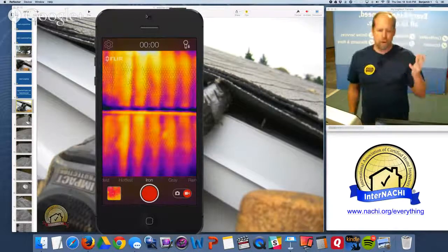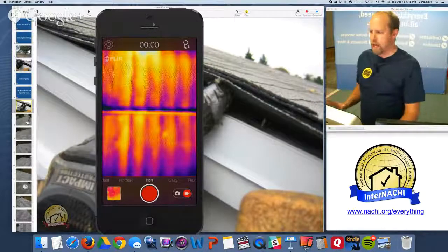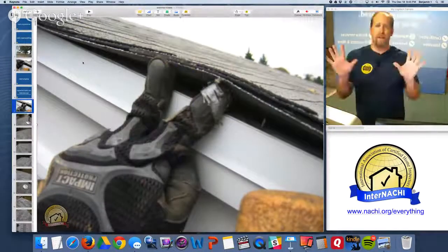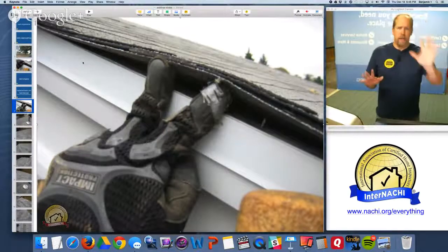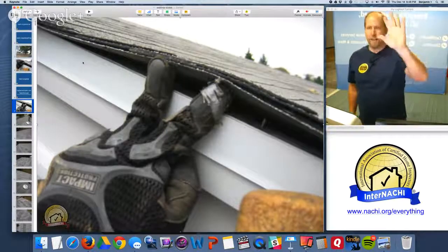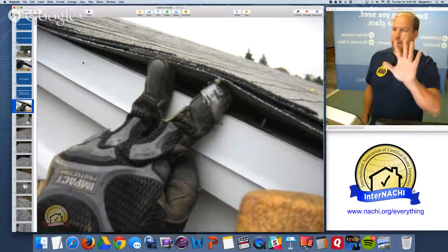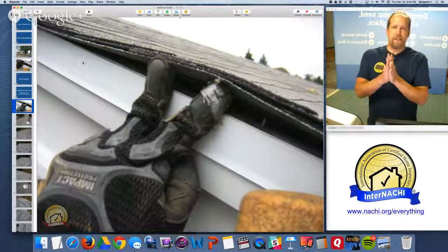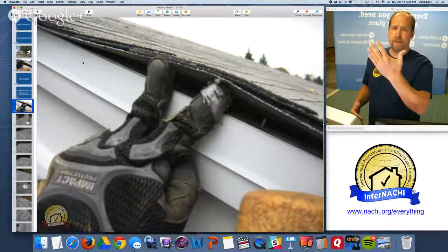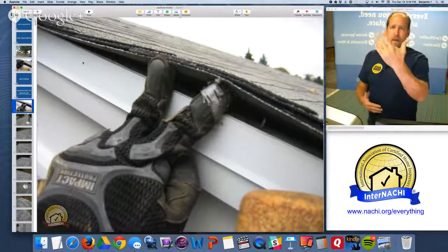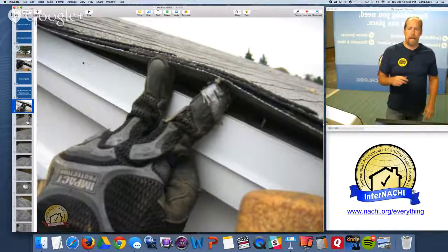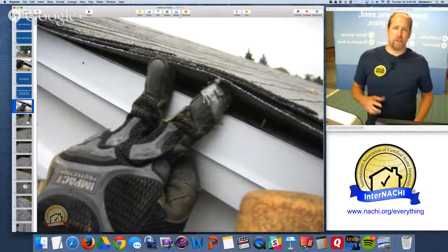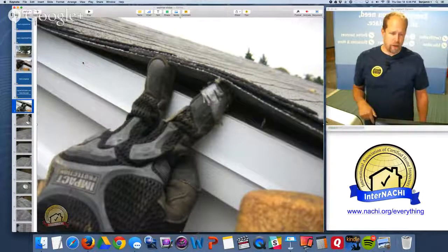But one of the best tools that you can carry is absolutely free. Every home inspector should carry one at your hand. This is one of the best tools you have. It's really sensitive. If you're looking for drafts or cool air, the back of your hand is really good. And I always put my hand in my inspections. Get my hand in there, and that's why I wanted to show you this picture.